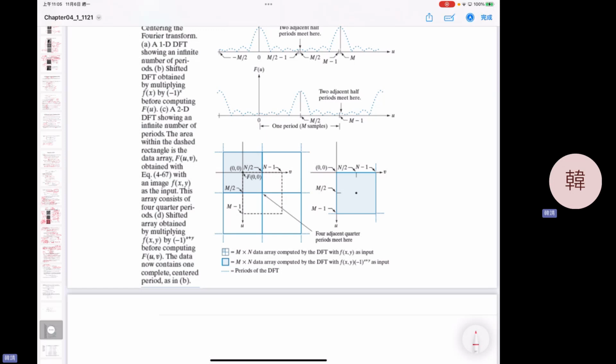And you have to expect the result, you understand, because it's long in vertical and narrow in horizontal, and the result should be like this. Why? Because in one dimension, this is wider, you get a sinc function magnitude. If you have wider, what do you get? You have narrower. So it's the basic concept of the Fourier transform: wider in the time domain is narrower in the frequency domain.